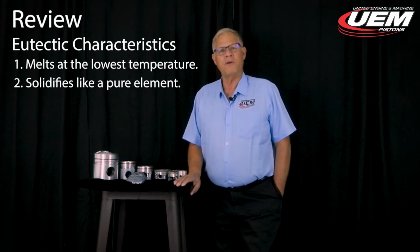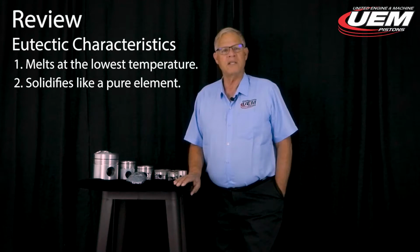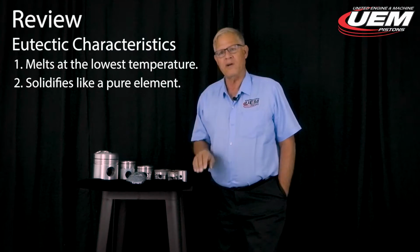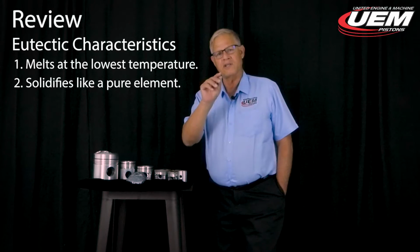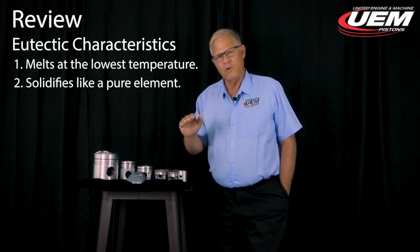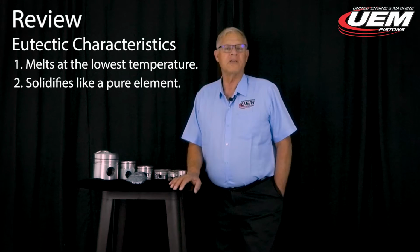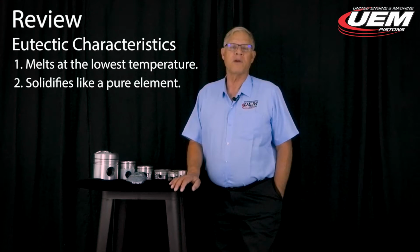And when we talk about pure elements, we realize that they solidify at a constant temperature all the way across. A non-eutectic alloy, when it starts solidification, the temperature will fall off as it's solidifying. So the second condition is that we solidify like a pure element.